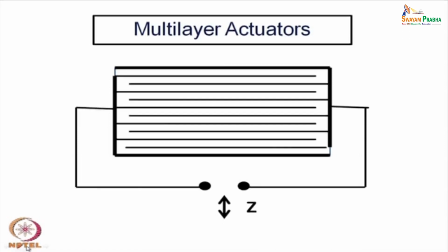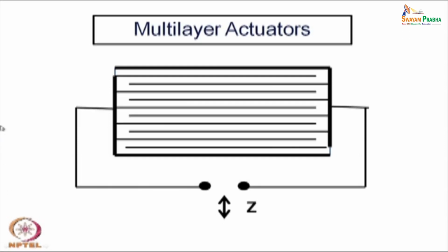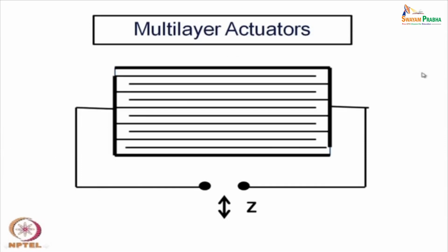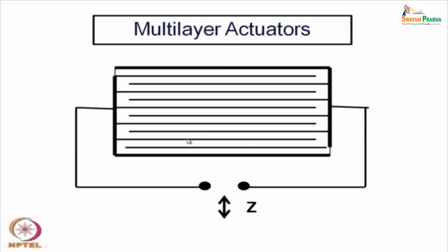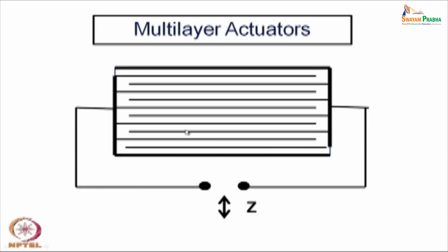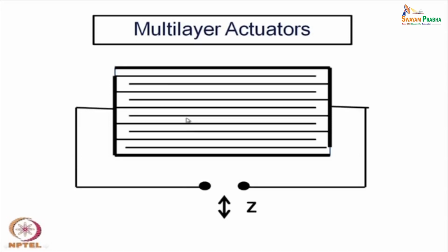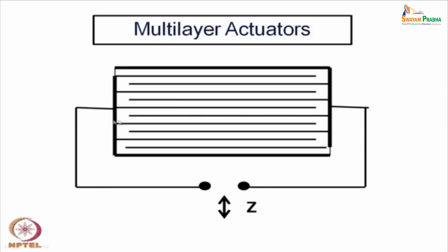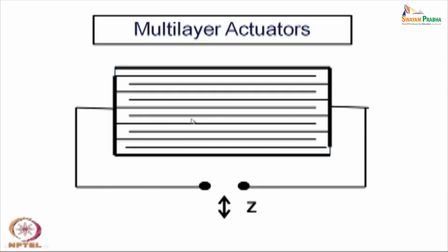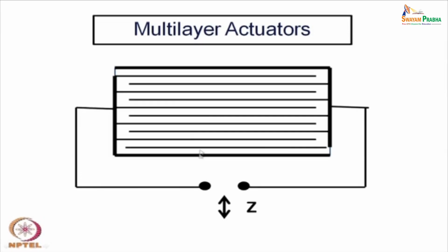principle is very similar to that multi-layer capacitor. Okay. So, there are very thin layers of PZT piezoelectric material, and then we have metal electrodes in the form of thin films, basically thick films. Right.